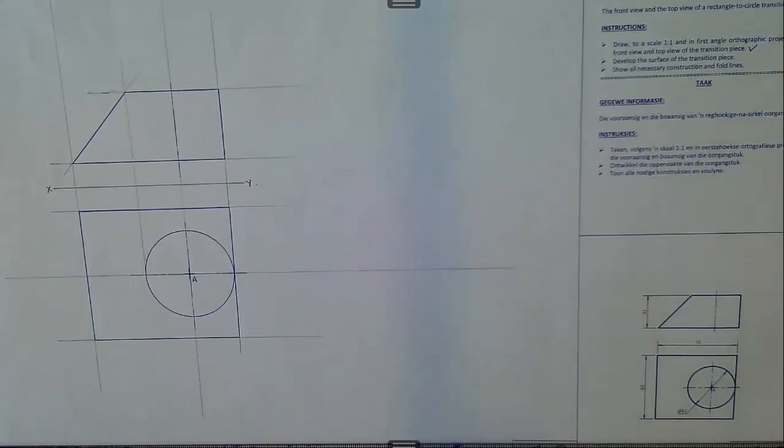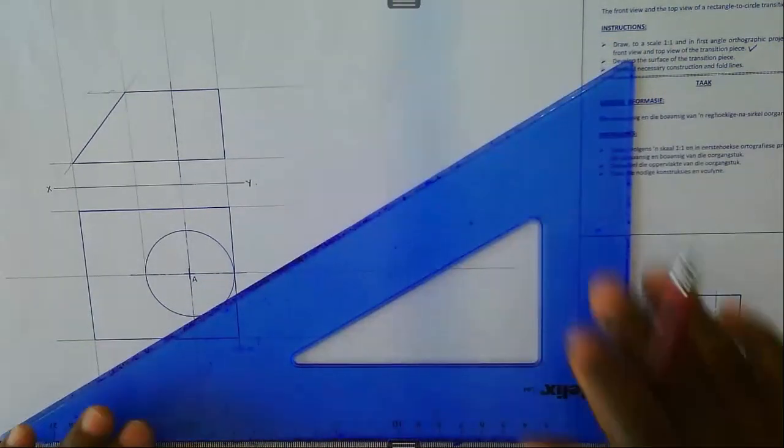But the next thing that we want to look at in terms of developing the transition piece, which is changing from a square base prism or pyramid to a circular geometric solid, which could be a cone or a cylinder. Okay, so we basically say it's from rectangle to circle. That is the change. So that part which is changing from one form to the other is what we refer to as the transition piece. Right, I'm going to divide the circle into 12 equal parts.